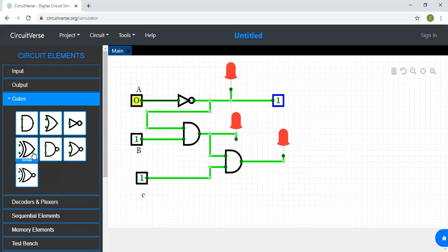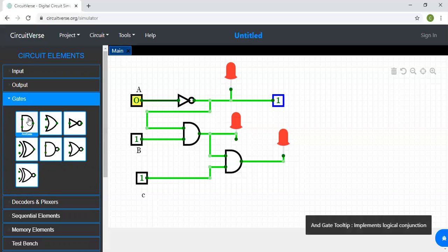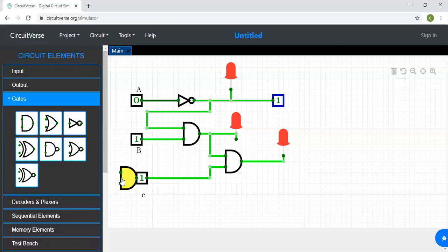Now in simulation, versus in real life when you're building a real circuit, you're really going to have to deal with the fan-in because circuits are only built at a certain input number. Usually, the more inputs, the slower the gate is going to be, the bigger it's going to be, and the more resources it's going to take. So a lot of times there are restrictions on fan-in. But let's just say we're in simulation, we can allow our fan-in to be whatever size we want.